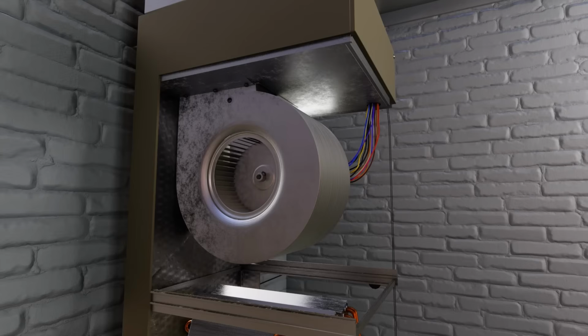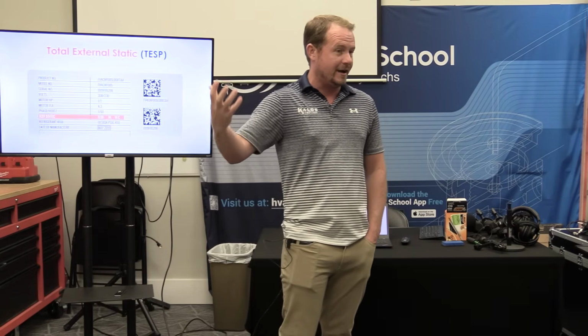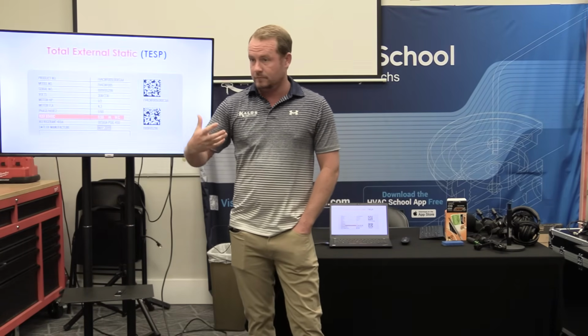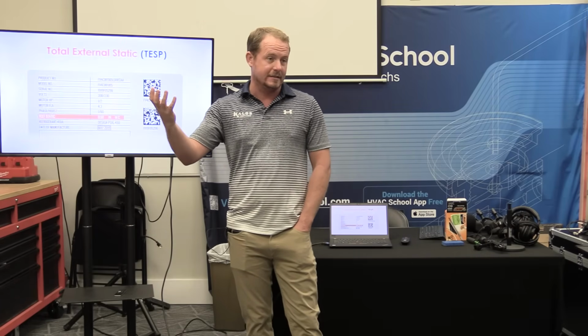on airflow. So if static pressure, the amount of pressure that it's working against, increases, what does that blower motor have to do in order to keep that same airflow? Hey, it has to spin faster, right? It has to spin faster in order to keep the same airflow. What do you think it takes in terms of the motor power when you have to spin the motor faster? It goes up, amperage goes up, right? So it has to do more work in order to move the same air.